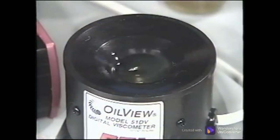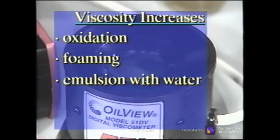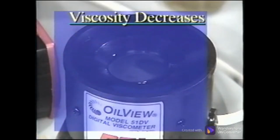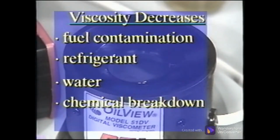Oil viscosity in a machine can change due to chemical, mechanical, or process influences in the system. Viscosity increases due to oxidation, foaming or cavitation in a pump, emulsion with water, solids contamination, and the wrong makeup lube added. Decreases in viscosity are caused by fuel or solvent contamination, refrigerant leaking into the system in air conditioning systems, non-emulsified water contamination, molecular shearing or chemical breakdown, and the wrong makeup lube added. A change in viscosity of 10% is a good indication of a lubrication problem, and checking viscosity is the simplest and quickest method to check for a wrong lube.